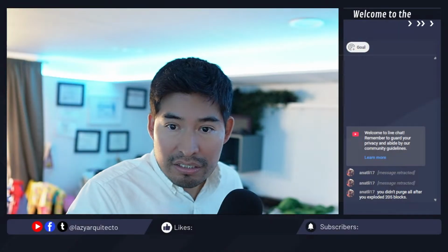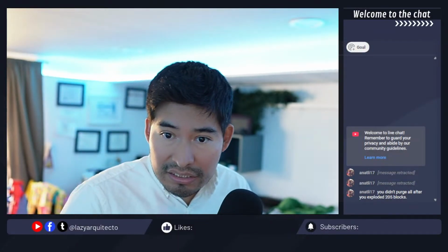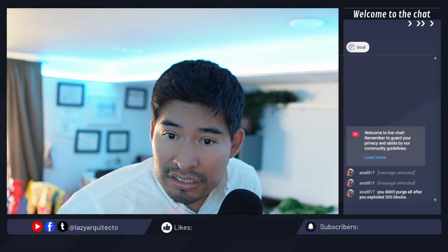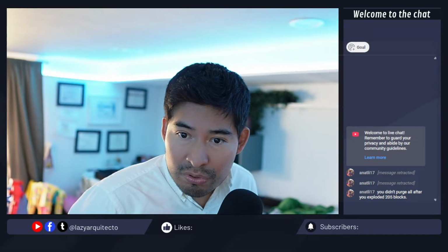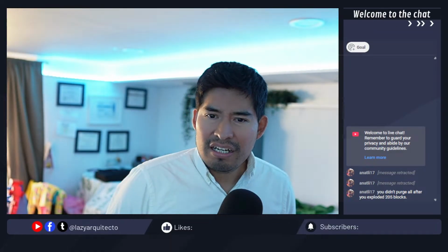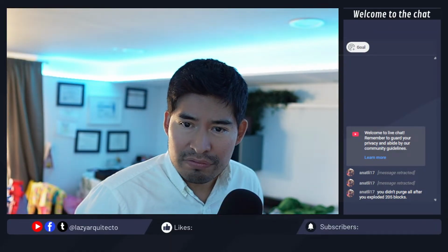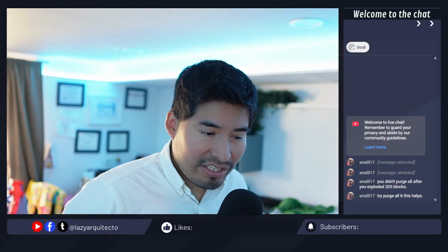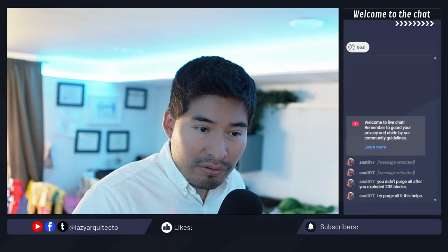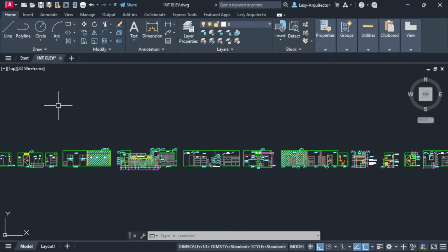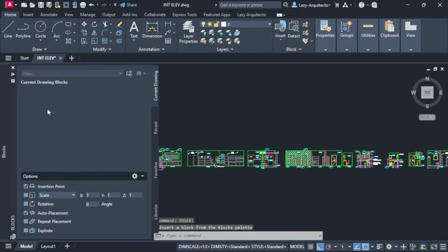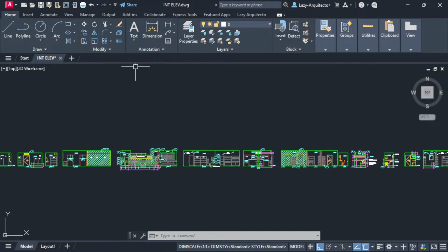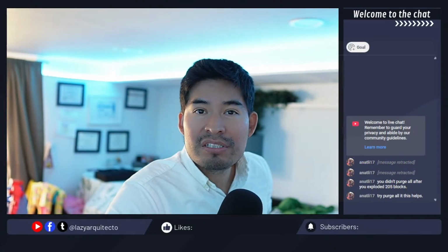It's our friend Analti. Hi Analti, hope you're doing great. Says you didn't purge all after you exploded 205 blocks. Yeah, I remember I did explode, my friend. And we also purged. We already checked that the blocks were removed. You saw that we used the insert command to open the blocks palette, and there were no blocks here anymore because we removed them all. So that wasn't the problem, Analti. We were able to discover the problem was the geometry.